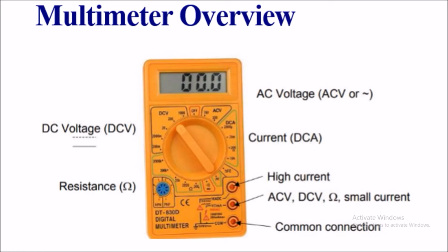This needs me to open the circuit, cut it, and connect the multimeter in series to measure the current. Another device is the clamp ampere. This does not need to be connected in series; it is like a ring. I open the ring and put it around the load. It will measure the current passing through the load according to the inductance, the self-induction generated by the flow of electric current in the conductor that I am measuring.